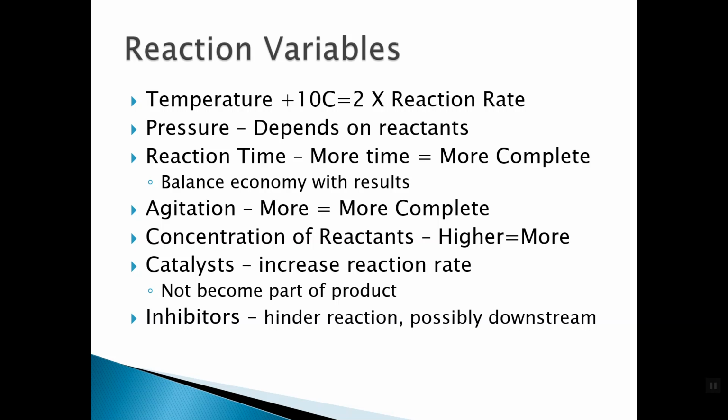Another thing is pressure. Pressure is not generalized as easily as the effect of temperature. Pressure can increase the reaction rate or it can decrease the reaction rate. In the ethanol reactor that we're going to look at, pressure will decrease the reaction rate because what we have in there is a bioreaction, which means it's actually a living, breathing thing. The yeast is what's doing our reaction. And if it's under pressure, it can't move around as freely. It can't do its job as well. And so that will actually slow down the reaction rate. Other reactors, such as reactors at the refinery, pressure will force those molecules together. It'll jam them into each other. And so it'll increase the reaction rate. So that really depends on the actual reactor that we have going on.